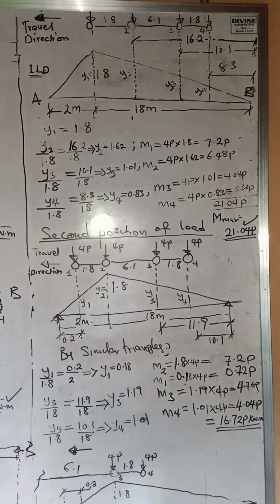So I believe with what we have done, you will be able to calculate the moment at any point on a simply supported beam carrying a series of concentrated moving loads. It doesn't matter how the loads are, whether they are symmetrical or not. You can do that conveniently. You can take the third position, which is 0.3 L, and analyze that to check the position of the load and the value for the maximum moment at that point, 0.3 L, as an exercise for yourself.